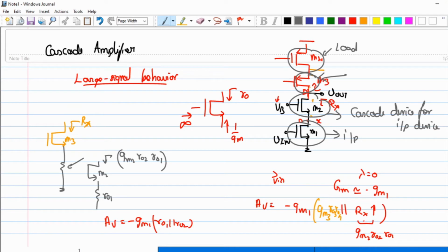Yeah, so nothing to worry. In case they specify the cascode dimensions, you should be in a position to tell which particular cascode we are talking about, whether M2 or M3. It will be clearly mentioned in the question. So if they state that the cascode device for the load has an aspect ratio of 100, then you have to take this M3 as its W/L factor, clear? So please make sure that you are comfortable with these namings, clear?